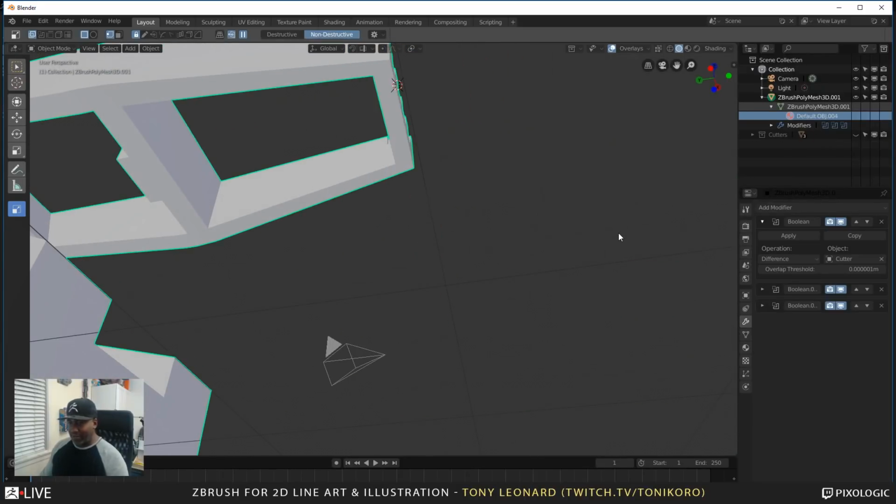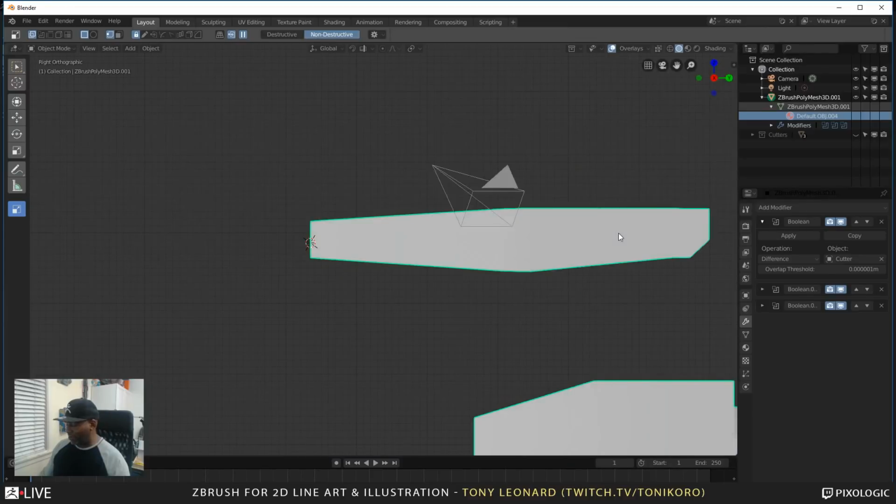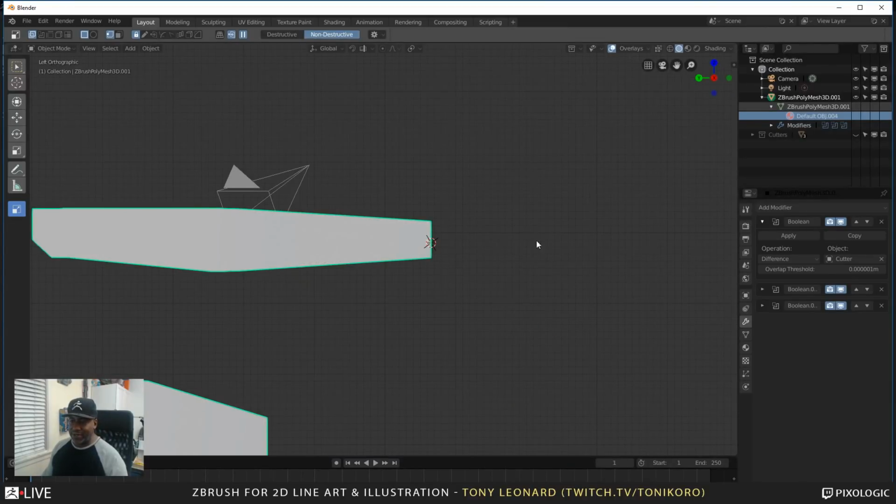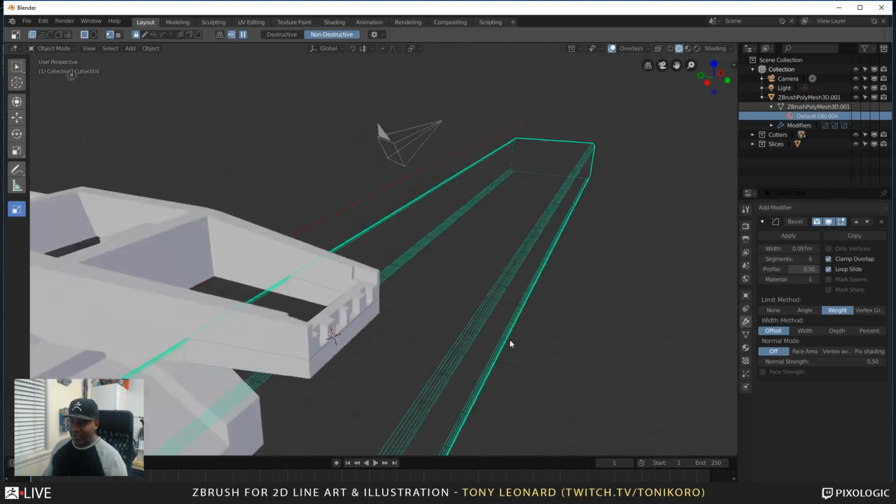So I'm going to hit escape, go 1, 3, 9, look at it from this side, drag out a box, hit X, hold this shape, and then I'll hit B and round off the corners because I want the rounded corner right in the middle there. And then I'll hold Shift and draw this shape out.